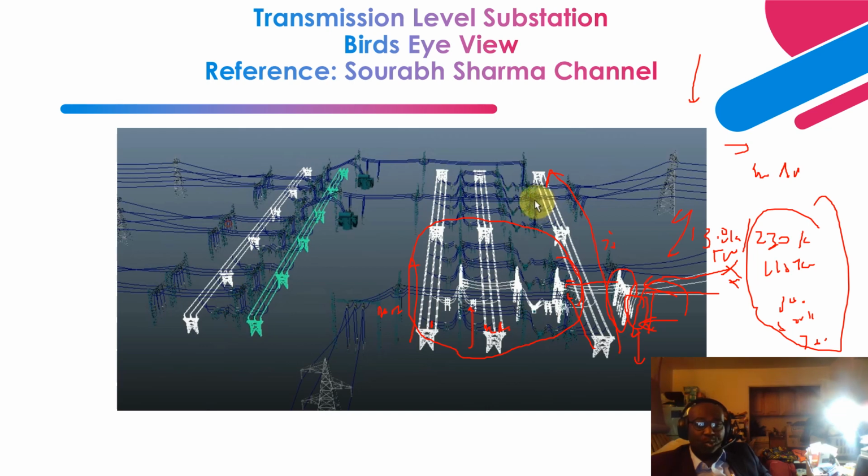Then it goes through this tower structure. Then there is a drop-down conductor that goes through a disconnect switch. From the disconnect switch, there's a riser that comes in here and connects this bus, so that you can feed power and voltage to energize this bus. This bus is in a 3-phase arrangement: phase A, phase B, phase C, in this horizontal arrangement.